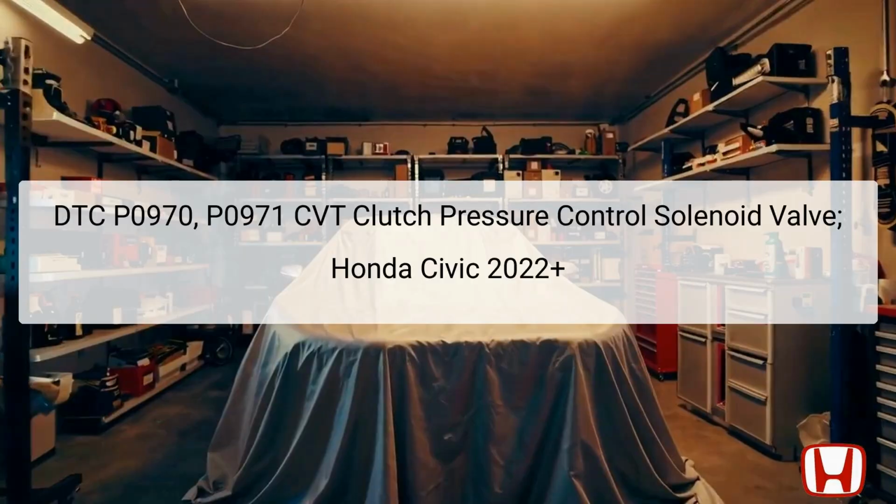The Honda Civic 2022 Plus may display DTC codes P0970 and P0971 related to the CVT clutch pressure control solenoid valve. DTC P0970 indicates a low circuit signal to the solenoid, meaning the transmission control module, TCM, is not detecting adequate current flow when commanded on. DTC P0971 signifies a high circuit signal, which implies an overcurrent situation.